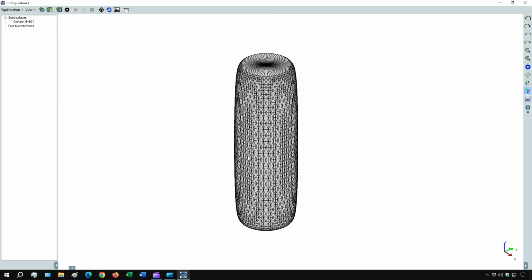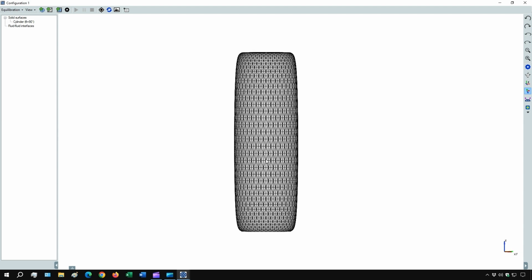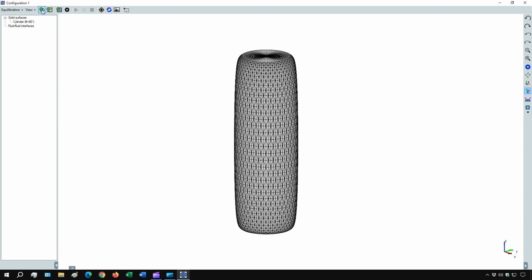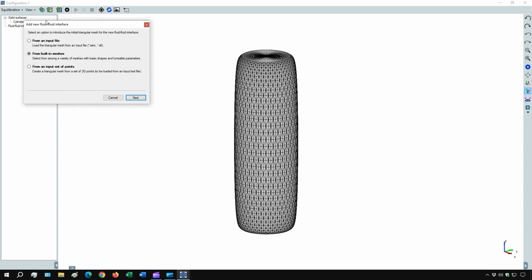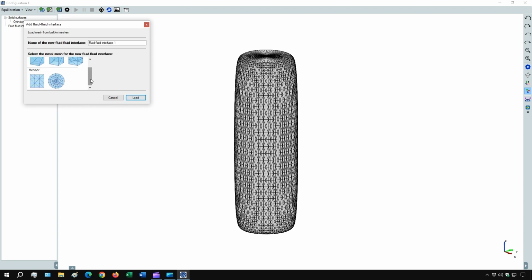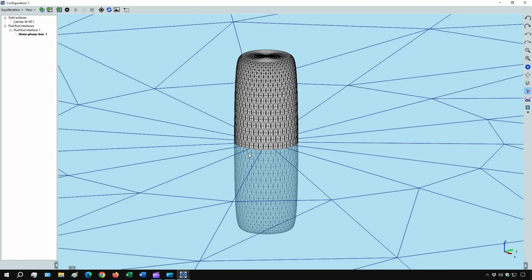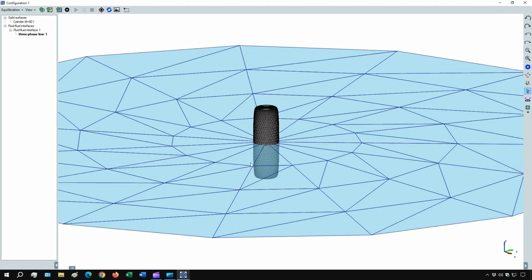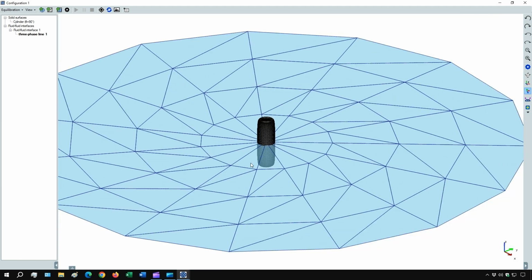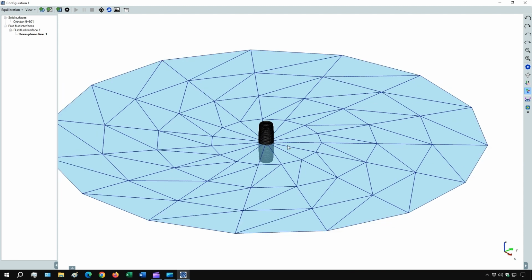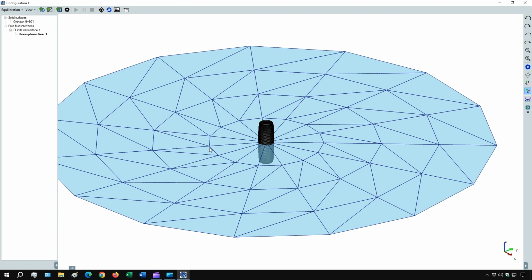We have now loaded the mesh for the solid particle. Let's now load also the mesh for the fluid interface. We select the circular meniscus, and we set an opportune radius that is large enough with respect to the particle size. We now need to create a hole in the meniscus center so that we can then use the particle as constraint for the boundary of the hole.